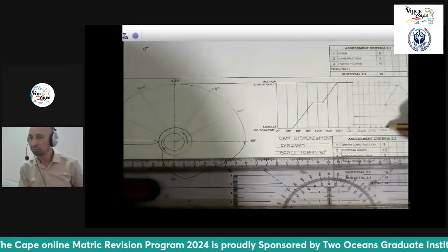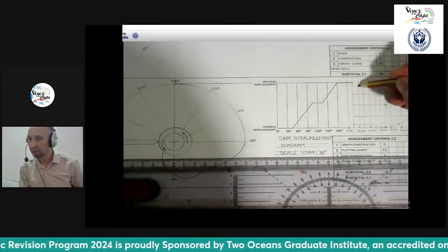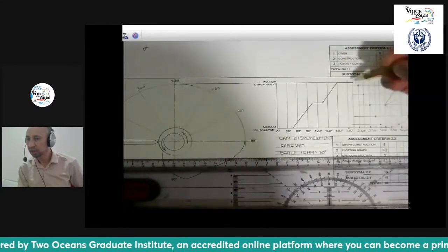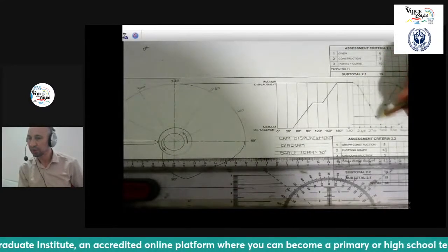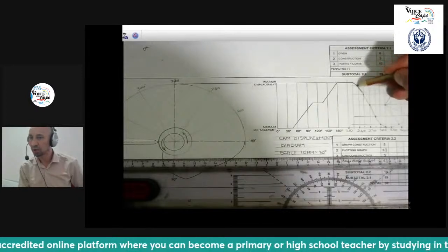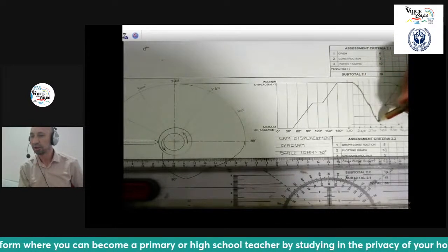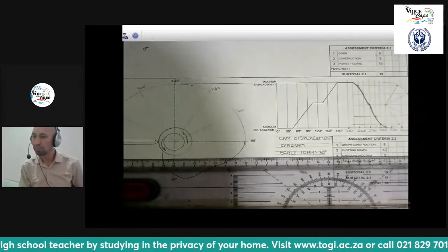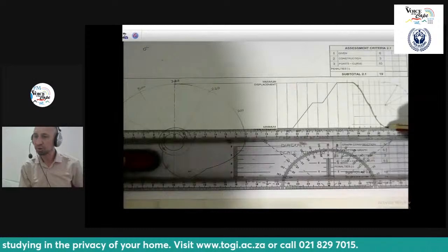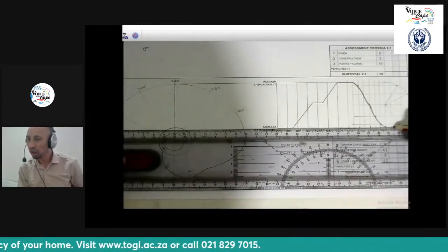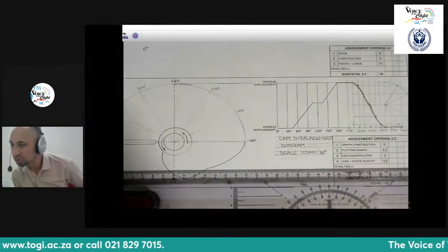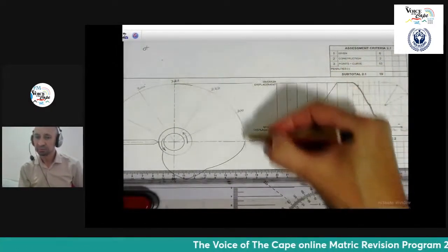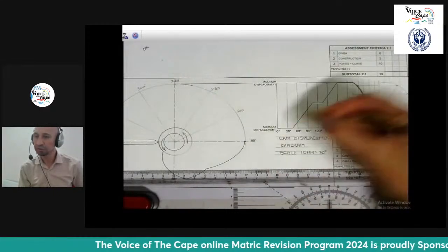And you will see now, I will simply plot one down, and move my way further, plotting points till the end, till my drop. Draw a faint line through it to get a nice and even shaped line going through all the plotted points. Then, of course, you can darken that, making it a nice smooth curve. Simple harmonic is this construction that we have there. And then the last one, it dwells for the last 45, which is midway between 330 and 360. That's the first part. The graph is now done.